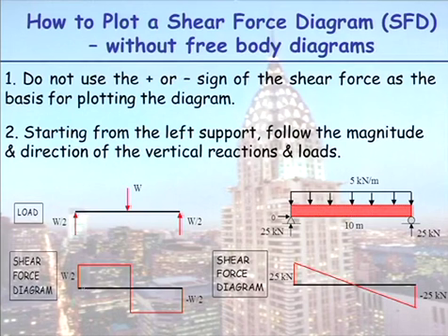So a shear force diagram, we start at the left-hand support, we step up a value of W on 2. Now, as we move along this beam, nothing happens. So we just move horizontally across this beam. Now, we're following the load. So suddenly, we step down. There's a point load here, a value of W. And that takes us from plus W on 2 to minus W on 2. As we continue moving along this beam, we don't hit any more vertical loads, so we just remain constant. And when we get to the end, we end up at 0, which is what we want to do, because all the forces in the y direction should equal 0.